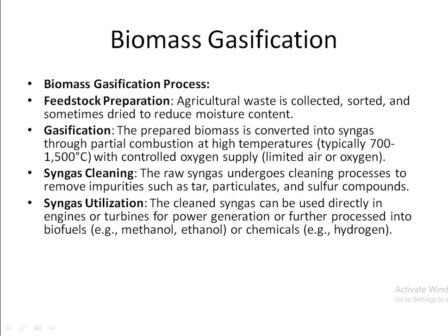Syngas cleaning. The raw syngas undergoes a cleaning process to remove impurities such as tar, particulates and sulfur compounds. Syngas utilization. The cleaned syngas can be used directly in an engine or turbine for power generation, or further processed into biofuels such as methanol, ethanol or chemicals, for example hydrogen.